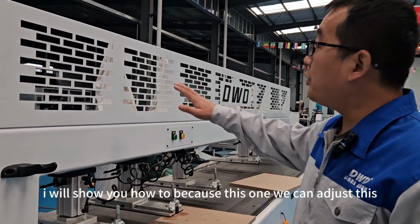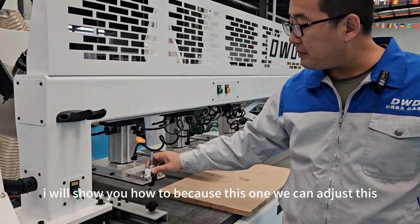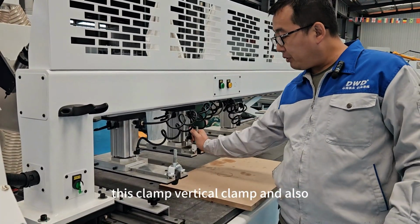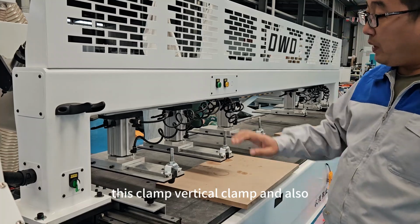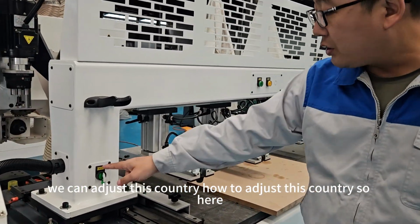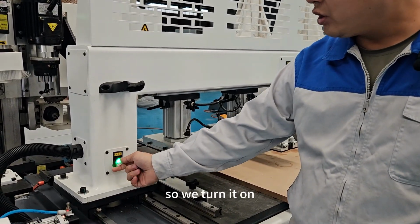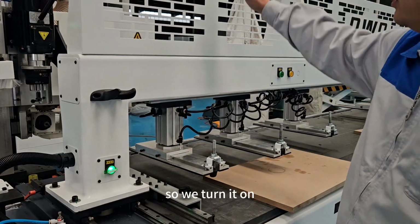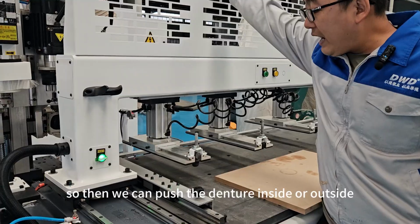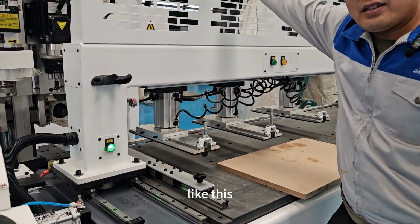So here I will show you how to, because this one we can adjust this clamp, vertical clamp, and also we can adjust this gantry. How to adjust this gantry? So here there is one lock switch. So we turn it on. Then we can push the gantry inside or outside, like this.